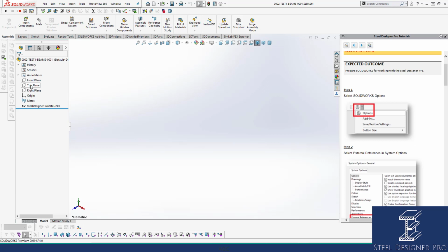So let's kick off a sketch on the top plane. Now all of our driving sketches for anything can be drawn on top plane, front plane, right plane inside of our welded member. So an attachment sketch is a sketch that's going to attach to another sketch. Our attachment sketches are important. They drive everything, and usually our attachment sketches, inside of assemblies, are drawn in the same direction as the driving sketch segment that we're going to attach to.